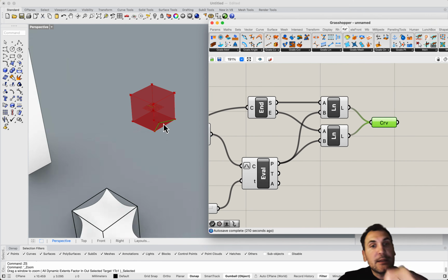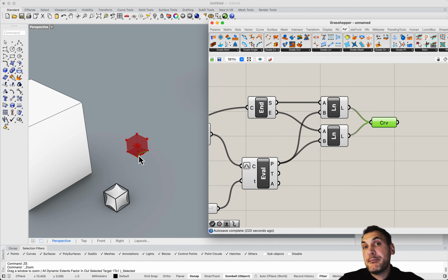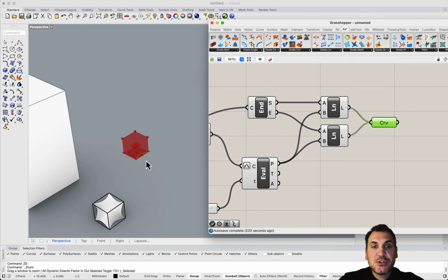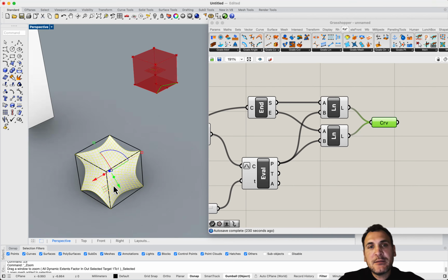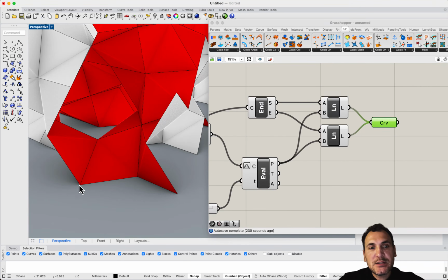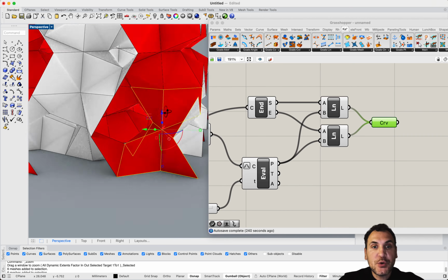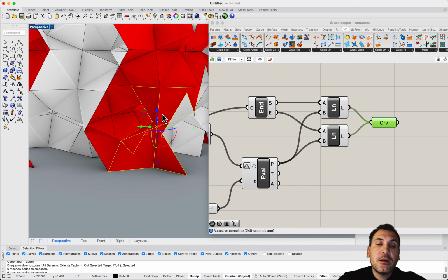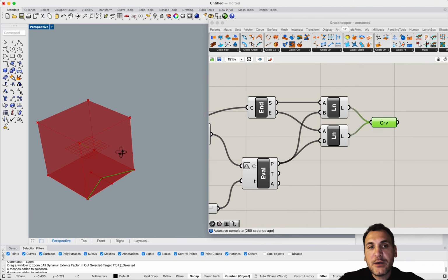Now, why am I drawing it like this? It's basically, we want to construct this as a mesh geometry. So for the mesh, this doesn't actually need all of the points. We can just work with triangles or quads. So essentially, as you can see, it has more faces because it's recursively segmented. But initially, we just want it to be defined as these quads. So we just need actually 4 points to define this as mesh faces. And then once you join these, you'll be able to subdivide it so it becomes smoother in geometry, actually. So it's kind of a way of handling topology.